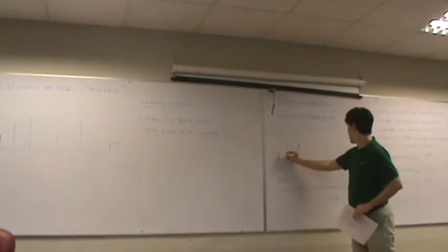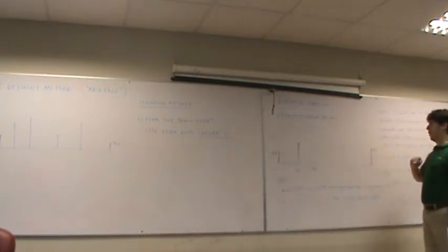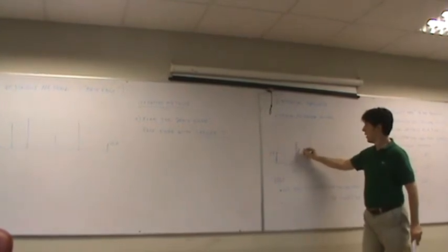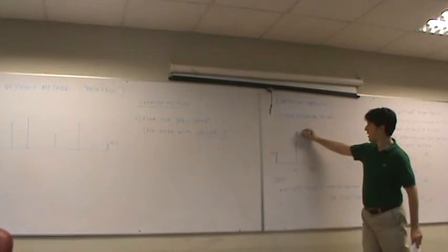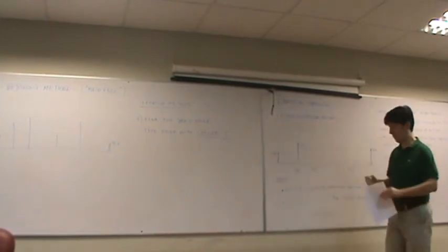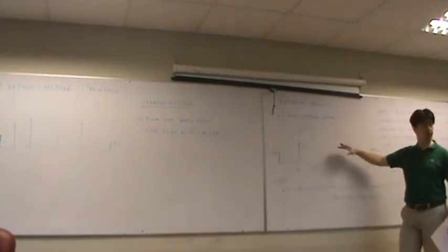So you draw a baseline from receiver to transmitter. Then you calculate this height, and from this height you calculate V1. This will be a different value of V with respect to the previous case, because we are ignoring the presence of all the other edges. So the baseline is different.